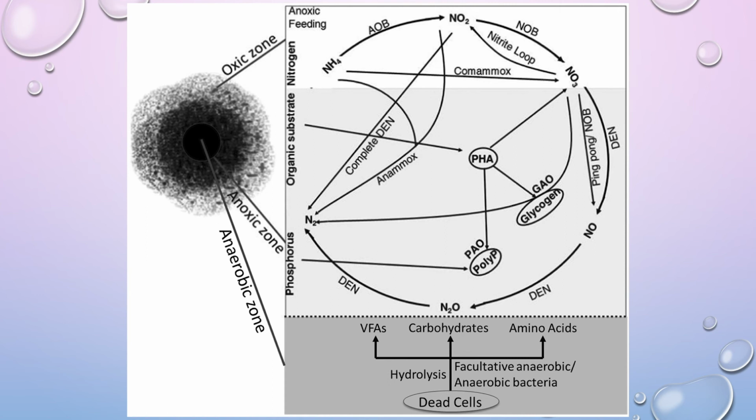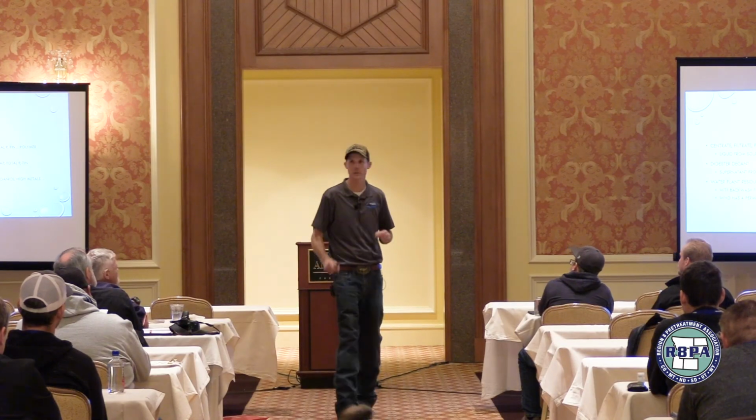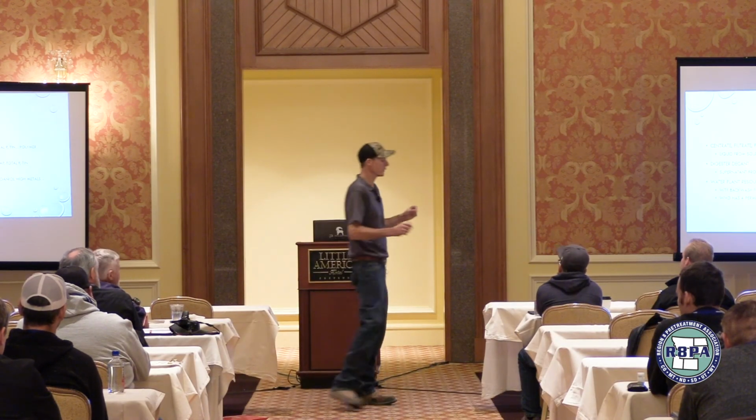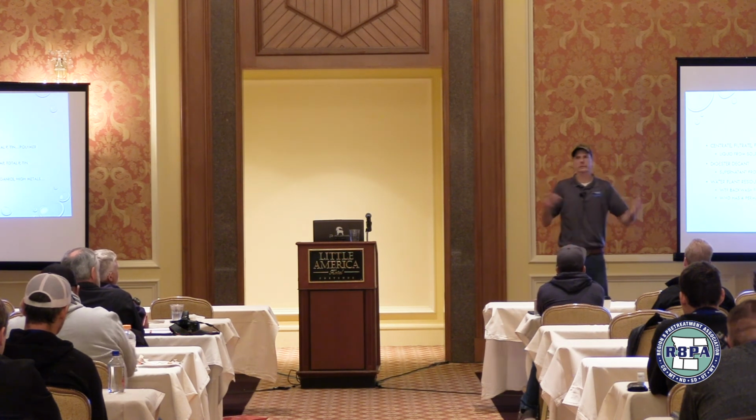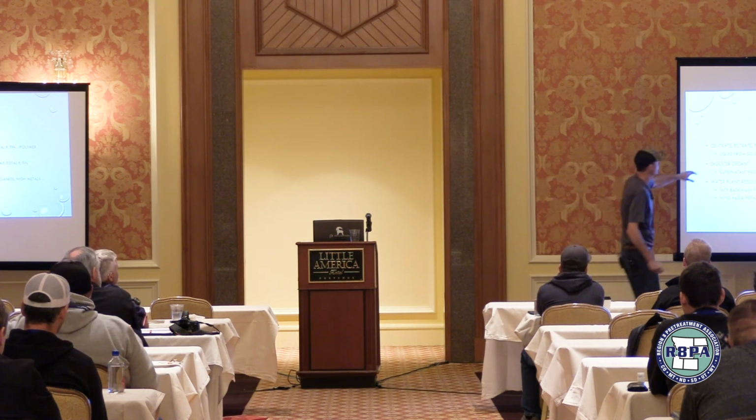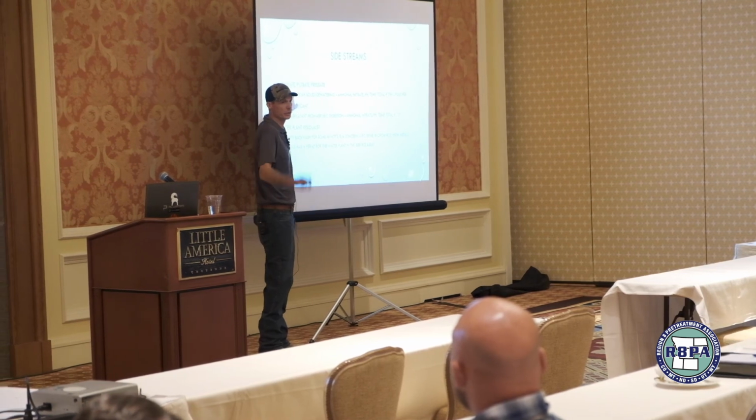Side streams. So this is where I wanted to get to. Side streams: centrate, filtrate, pressate. As a pre-treatment person, you don't ever see this. But this is something that will directly affect your removal efficiencies. When you're doing your local limits development, you're thinking about how much ammonia, zinc, whatever. You're thinking heavy metals. All your heavy metals end up in your digester, they should.